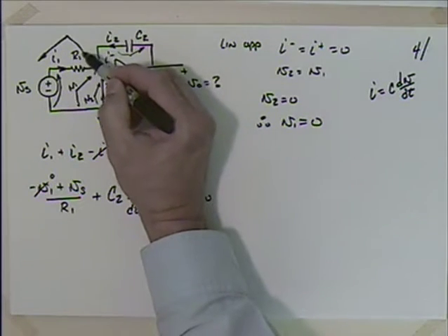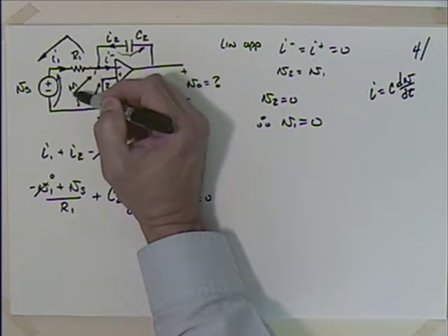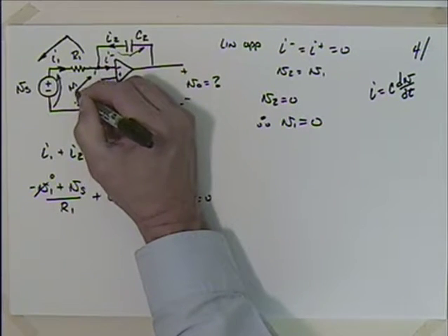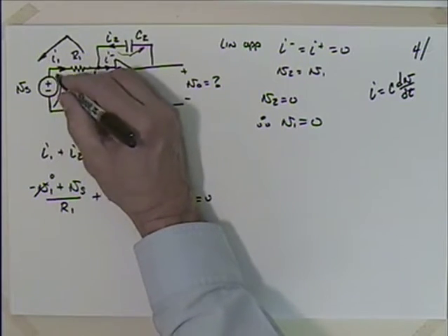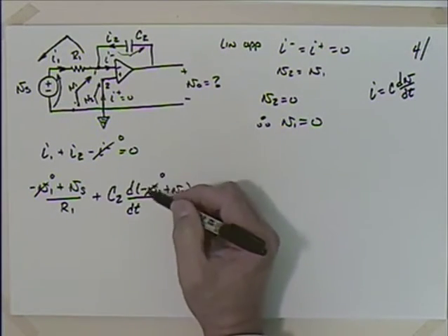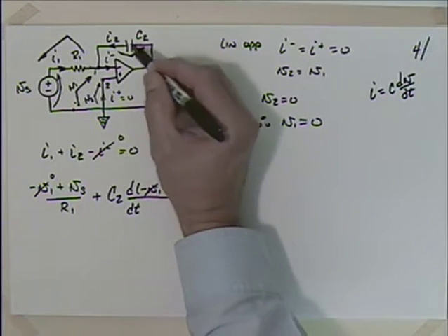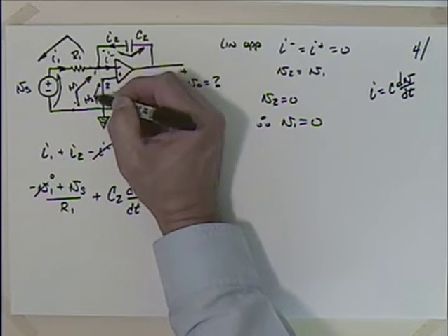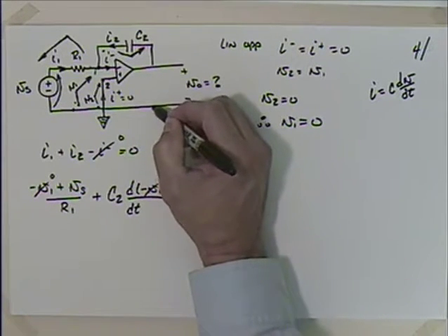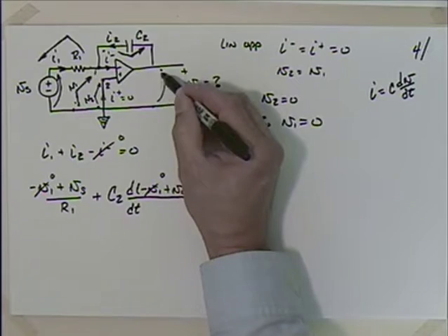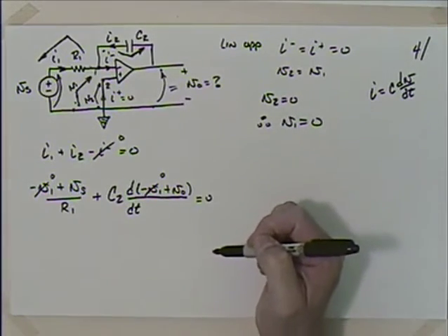I want to try and find the voltage from this point to that point. So I go minus V1, because V1 by definition is that. So minus V1 gets me down here, and then Vs gets me back up there. Let me double check the voltage across this. I'm trying to go from there to there, right? So if I go from there to there, that's minus V1. And then back up here from the ground state, that's by definition V0. Good. I think we're okay with that.